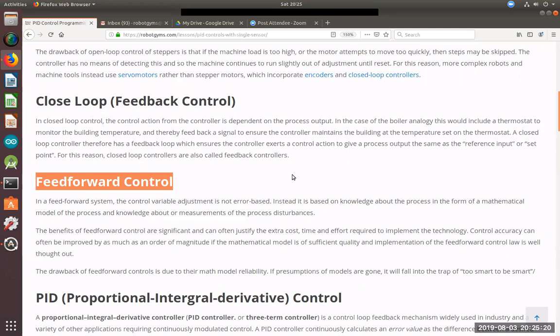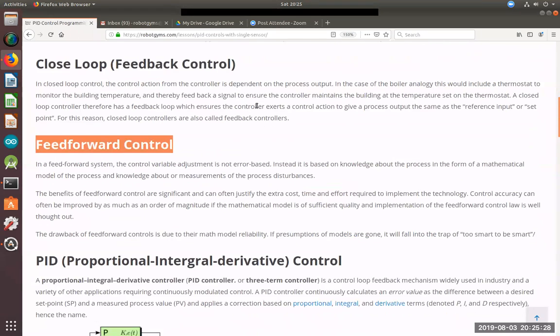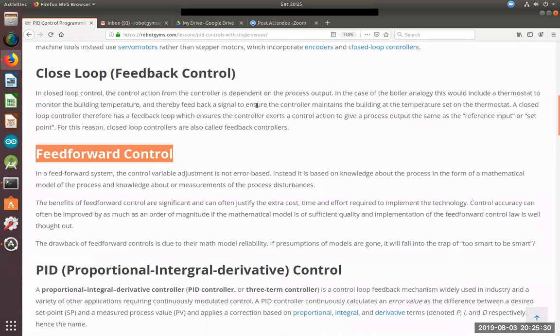Okay, we still can do it. There's one term in PID control, D. D means derivative. Basically, look at the trend, right? So suppose you want to move 90 degrees, right? In the beginning, you apply huge power, so robot swing really fast. And when robot find out you apply big force, the gap, the error decrease really fast. Then what robot should do?